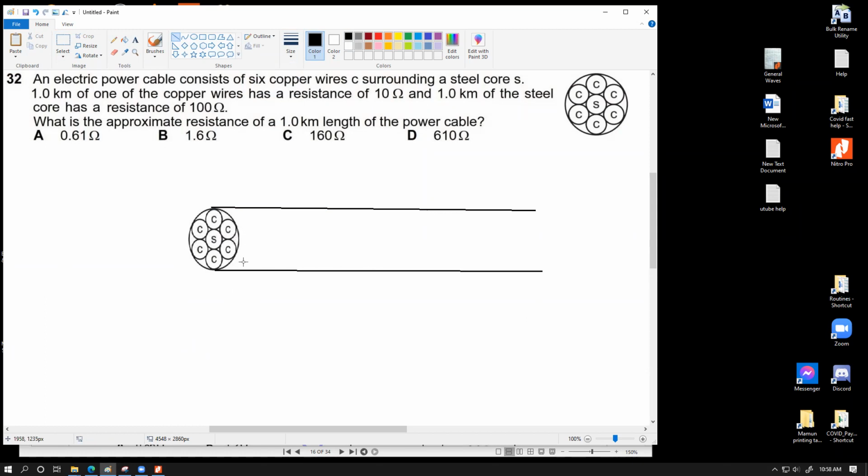but I want to tell you that steel practically gives the strength of the cable so that it can hold up its load, so that you can hang the wire with large gaps between the poles and use fewer poles for the whole transmission line. The steel is there for the strength, and copper is there for the higher conductivity, so that you have less loss and less heating in the wire and you can transfer more electrical energy to the consumers.